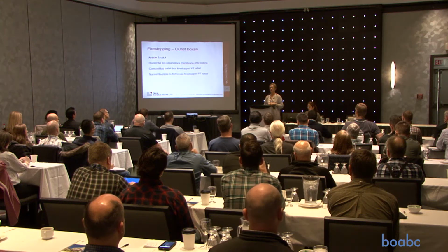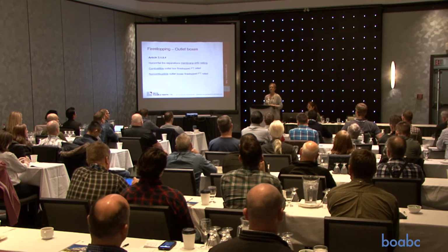So it seems to me that if tightly fitting the box will fix the problem, so you don't need a fire stop, then the fire stop goes in the annular space around the box. And I've had a million conversations with Hilti, and Hilti says there's no putty pad that would pass the T rating in a ceiling scenario. It will in a wall, but only because it's way down here.